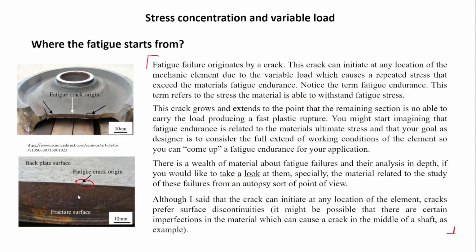Either because when you manufacture the part, in the process, something, it's a micro, not a failure, but kind of an irregularity started on the surface, and then everything went downhill from that. Of course, cracks can exist also in the interior of the material, and that would depend on the quality of the material you are using.